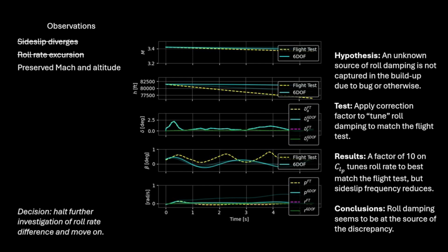There are many other flight experiments we can compare to that'll help us uncover the reasons the simulation and the flight test may disagree. What about the longitudinal dynamics in this simulation? While the longitudinal dynamics easily decouple from the lateral dynamics under a steady wings level assumption, the lateral dynamics only decouple under steady wings level with small state perturbations. If we violate the small perturbation assumption, we must also capture the longitudinal dynamics coupled to the lateral for accurate lateral dynamic prediction.